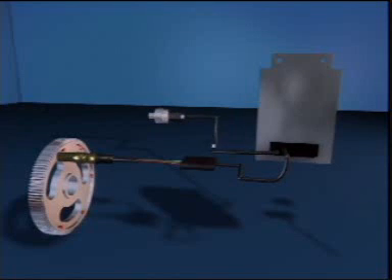The intake manifold pressure sensor is a transducer that generates an input signal to the ECM proportional to the air-fuel mixture pressure in the intake manifold. The ECM uses this signal to adjust the base timing and as an input for air mass calculation. Remember, the manifold pressure after the throttle plate may be different from the turbocharger boost pressure.